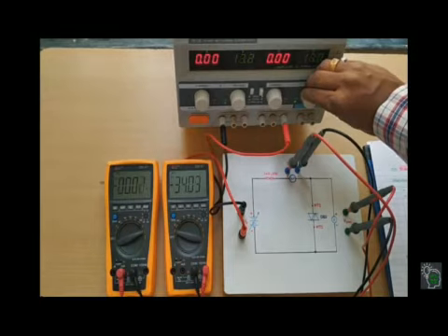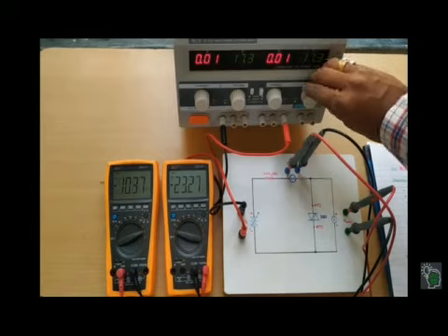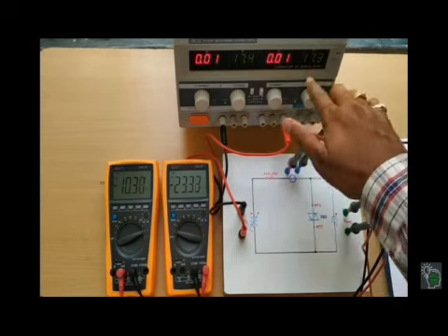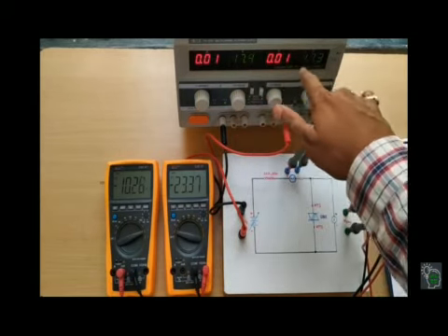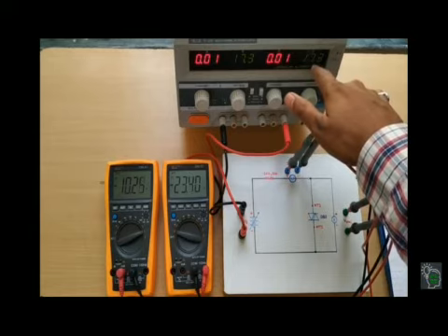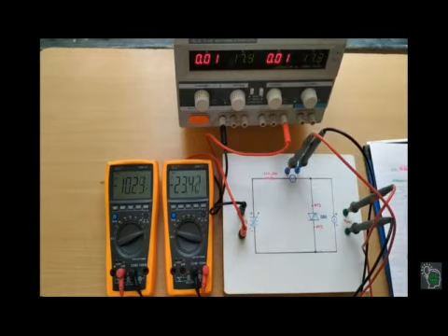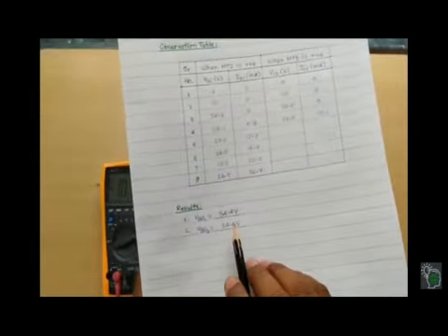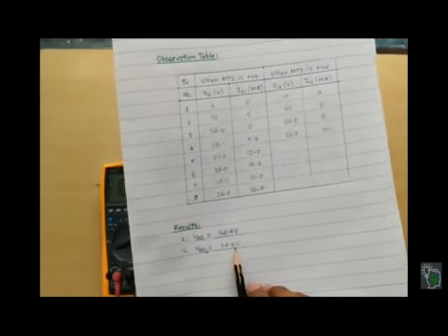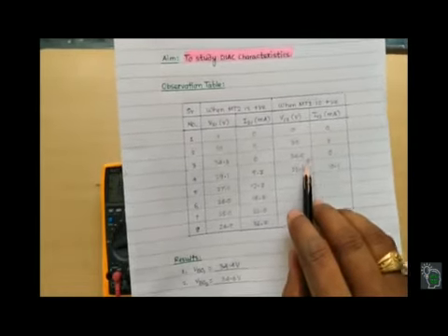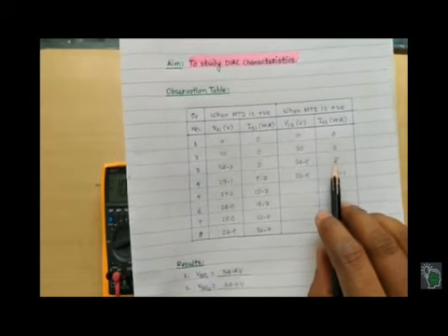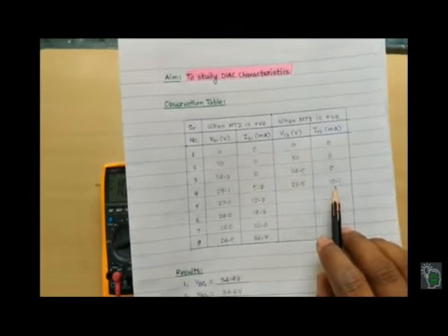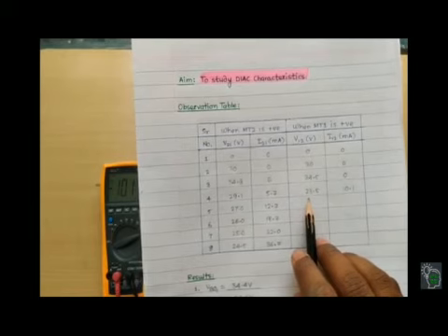At 34.10, same, 34.3 volt. At the point of 33.4 volt, suddenly voltage decreases and current increases. Here are the readings: 34.6 volt, or we can say 34.5 volt, suddenly the voltage drops and the current increases to 10 milliampere.